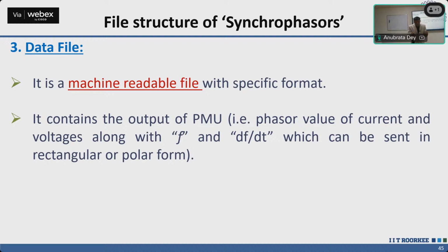So inside this PMU, they do the phasor estimation. They run the phasor estimation algorithm, and you are well aware of it. You can use the discrete Fourier transform, you can use the cosine transform, you can use LES, the least error square technique, or you can use Kalman filtering, or maybe anything else. So these are the main four techniques used for phasor estimation. Each has certain advantages and disadvantages.